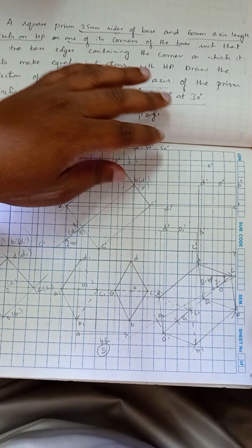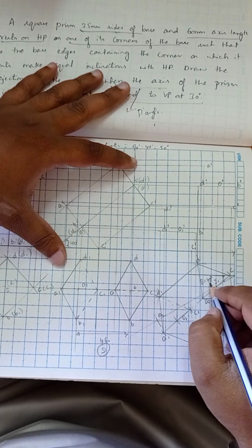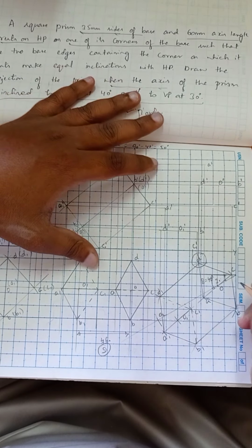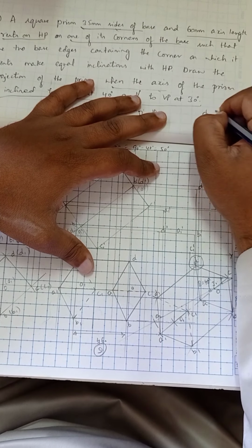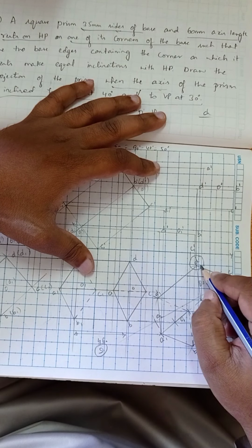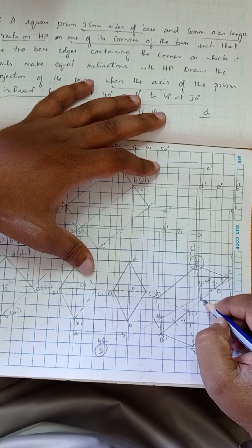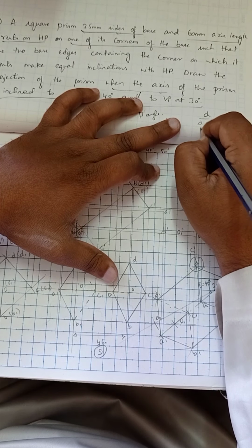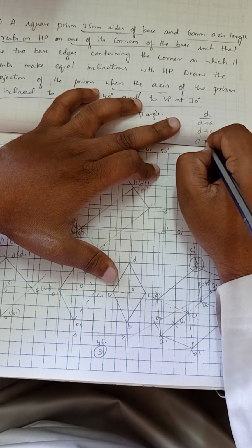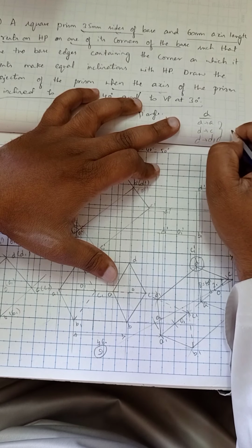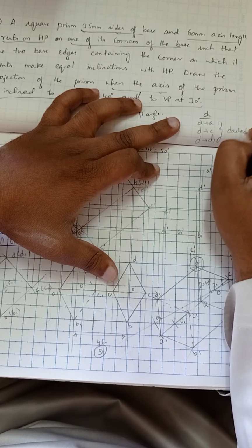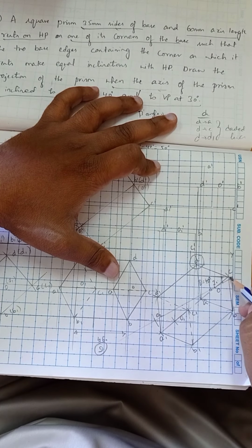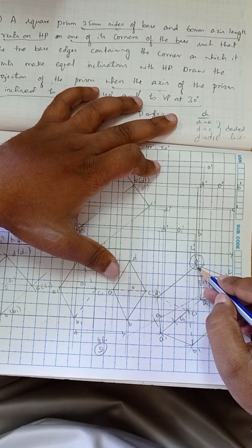Okay, so we have done this. Now we know the concept. We have to consider the nearest point to the x value in the top view, that is the fifth position, D. So D is the nearest point, correct? D is connected with C, D is connected with A, and D is connected with D1.